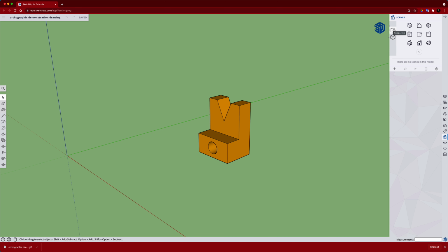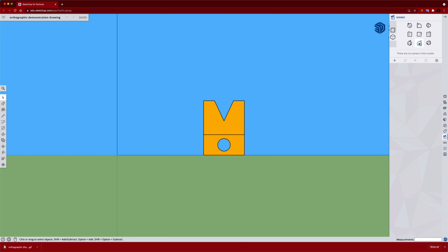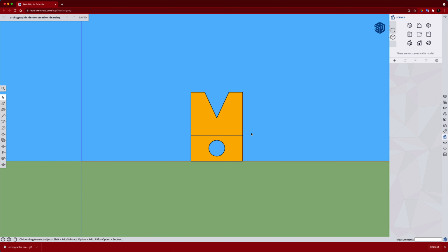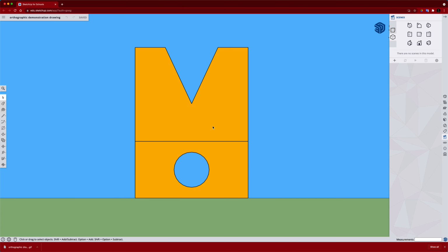But when we want to look at specific views like the front view, right side view, and top view, we want to click on this one down here, which is parallel projection. Now, in an isometric view, it sort of skews the parallel projection. It looks really sort of off. Okay, but looking at it from a front view, you can see we get a true front view right there. So literally, when we draw our image for the front view, that is what it should look like.